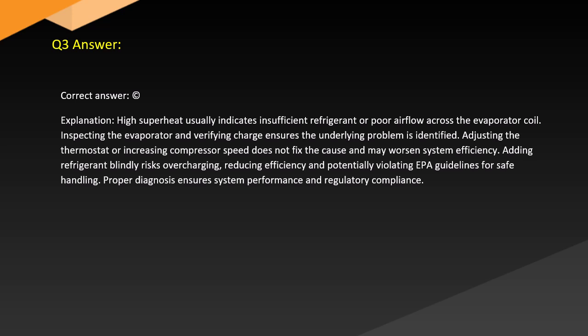Adjusting the thermostat or increasing compressor speed does not fix the cause and may worsen system efficiency. Adding refrigerant blindly risks overcharging, reducing efficiency, and potentially violating EPA guidelines for safe handling. Proper diagnosis ensures system performance and regulatory compliance.